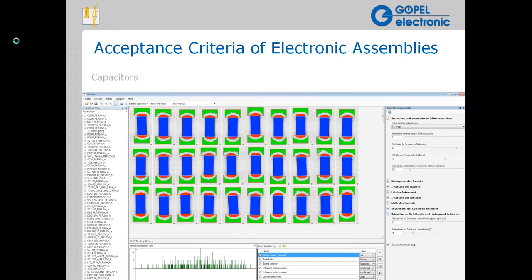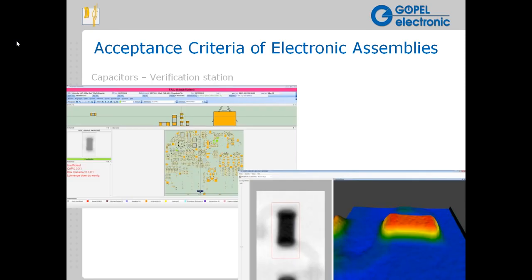To talk about BGA solder joints in a little bit more detail, this is naturally a very active subject in X-ray inspection. BGAs pose many challenges. They pose challenges to electrical test due to lack of accessibility. Goepel actually deploys and develops a very robust line of JTAG boundary scan related products to help with electrical tests and these kinds of challenges. But for optical inspection, X-ray is really the answer for BGAs. There's very little that you can do from an optical standpoint for a BGA, but with X-ray you can reveal a very great deal of detail.